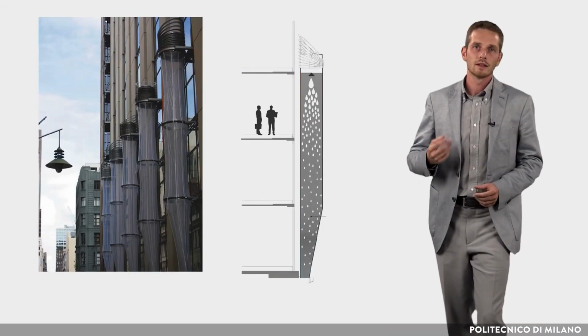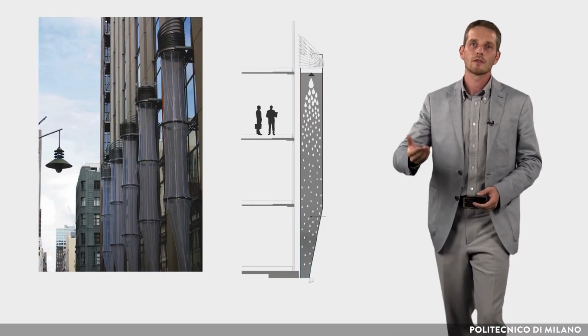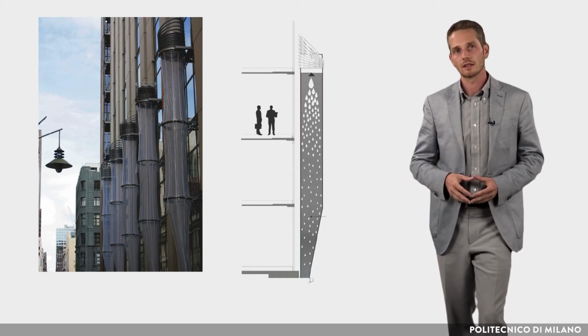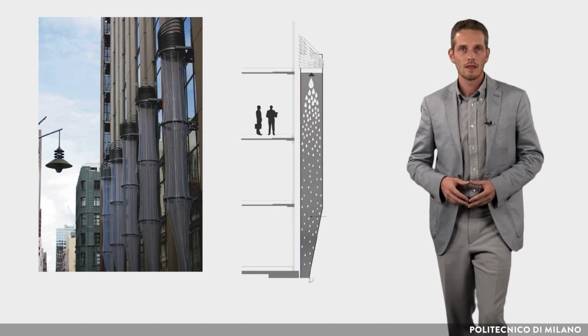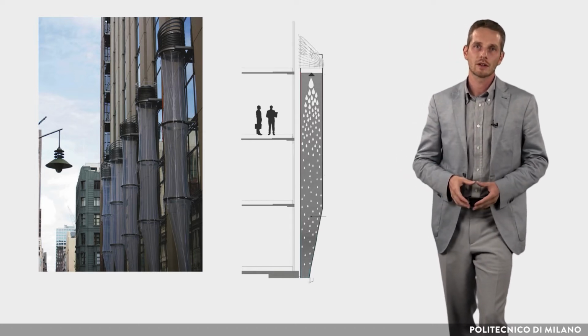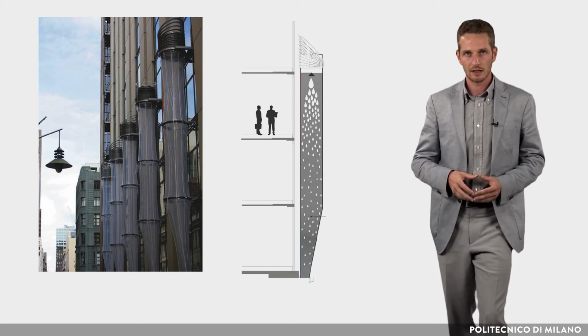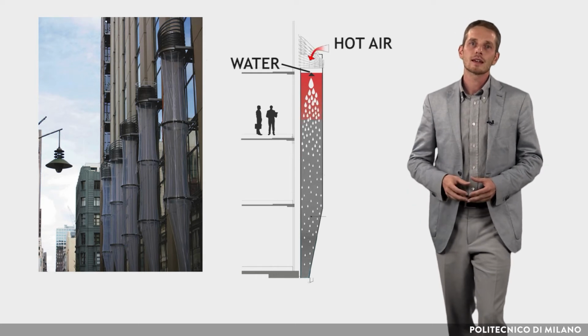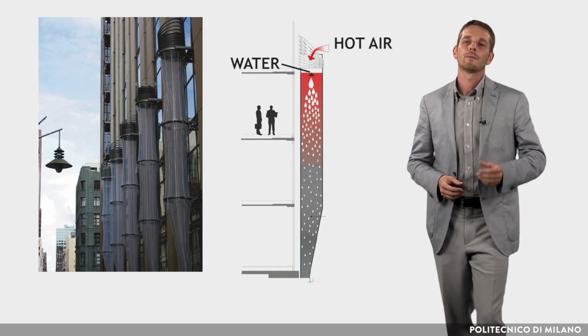In the second one, the showers along the southern facade of the building cool the air for intake and use it in the ground floor. The showers are made from tubes of light white fabric 1.4 meters in diameter. As the water falls within the tower, it sucks in air from above.